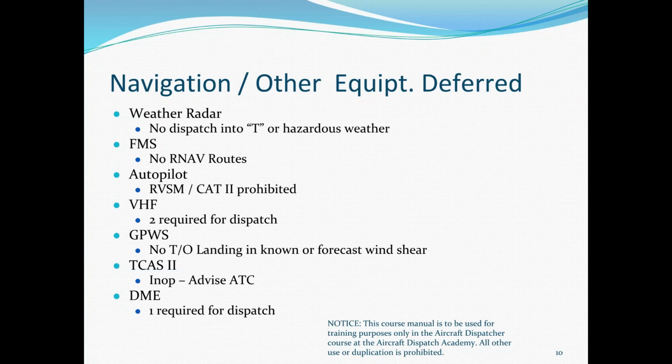If the pneumatic system's not working, well, the pneumatic system on 99% of the turbine aircraft out there, guess what the pneumatic system operates? The ECS. It's going to operate anti-ice. It's the bleed air that supplies the engines for engine starting, things like that.